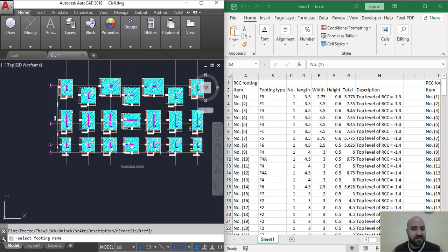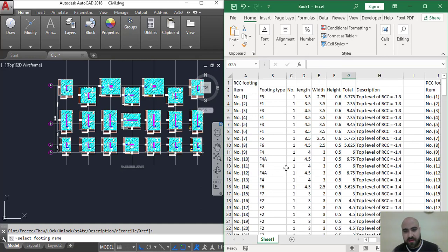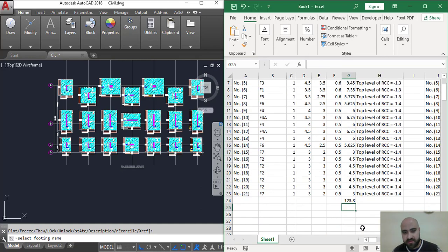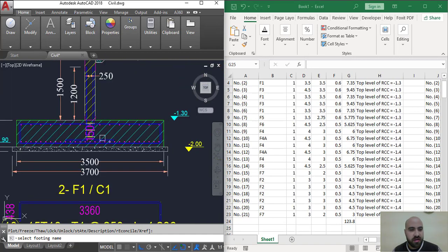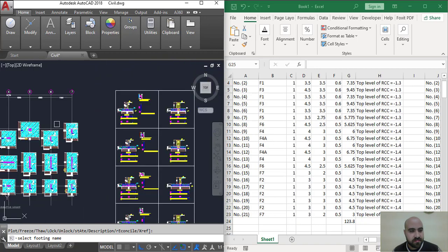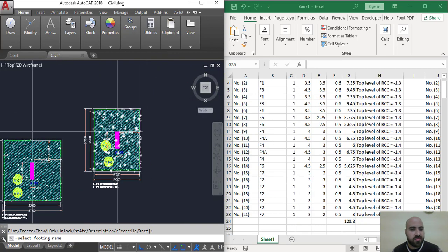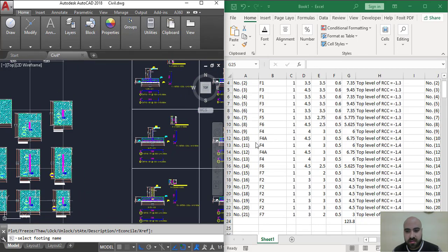After we have done all of these footings, this is all of the data here. This is the final quantity for reinforced concrete footing. And also we have here the full shop drawing for neck columns and the reinforced concrete footings and PCC. And everything, if you want to remove this hatch, just isolate it, all of this, put it in a separate layer according to its element.